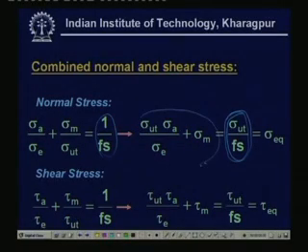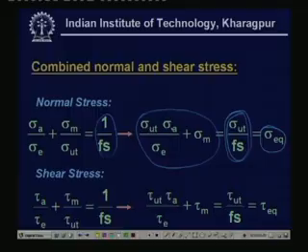So, once it is the concept of the design stress, why not call this entire part of the equation a stress which could be read as sigma equivalent. The sigma ultimate divided by factor of safety we consider in static design to be a working stress, and in a similar manner for fatigue design, sigma ultimate into stress amplitude by sigma E plus sigma m is somewhat like a sigma equivalent stress.